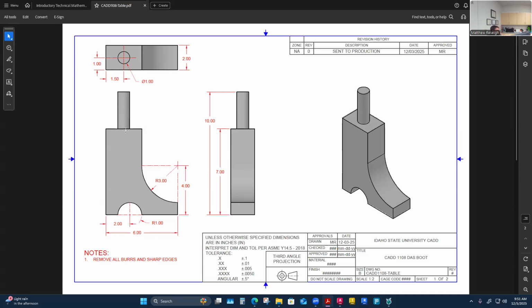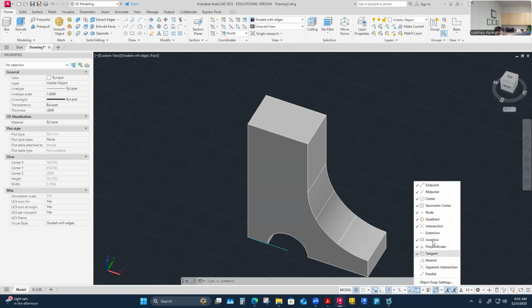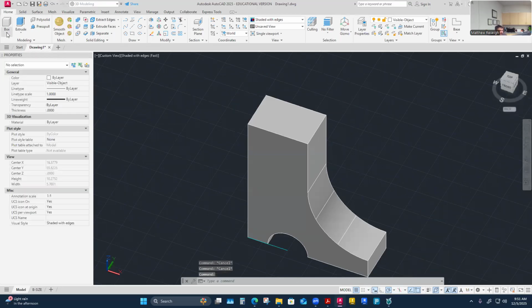And one of the 3D grips is center of face or geometric center, right? So if I come over here, I just want to place it in the center. Center of face is definitely a 3D grip that I have. The 2D grip might recognize that it's also the geometric center of this shape. So maybe I've got a couple grips that'll fire off. But what I want to do is a cylinder, another cylinder, move here.